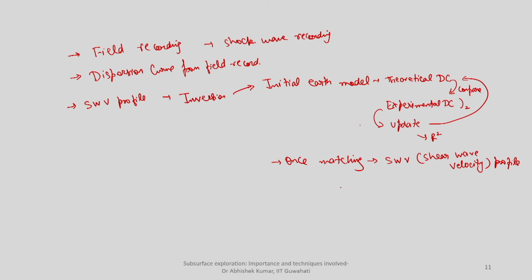that is, shear wave velocity variation with depth, that will identify stratification details. So, this is what I tried to give here, an overall idea about what the surface wave method is, and what the advantages are when we go for surface wave methods in comparison to body waves.